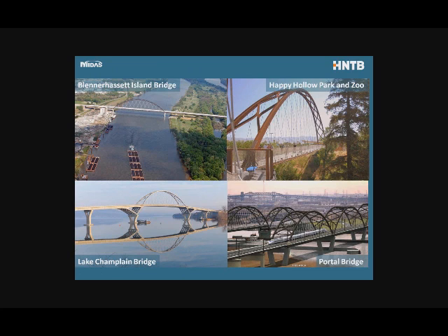This is going to be a railroad bridge designed for 2 Cooper E80 loads. These are very heavy loads. I did the numbers yesterday, it was like 8 times the normal, or about the equivalent of 20 lanes of highway loading. So this, if it gets built, is probably going to be the highest loaded network tied arch in the world.